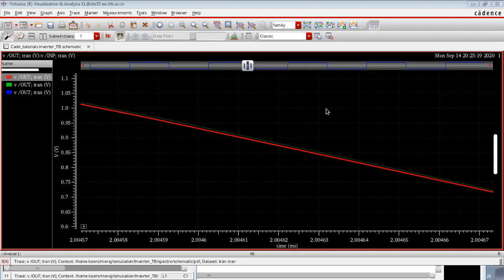There are various design techniques. Can we make a circuit such that, like when you study negative feedback in op-amp designs, even if you have process variations, you will get a fixed gain because your gain is dependent on R1 by R2, like an inverting amplifier. So what we will do, we'll have a very high open loop gain and we'll use passive components.